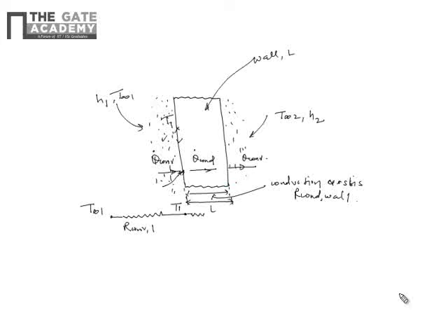Now the wall is offering some conduction resistance, and its wall temperature has dropped to T2 on the right hand side surface. Again at this surface there is one convection resistance on the right hand side that will cause the temperature drop, and as we know, the right hand side fluid temperature is given as T∞2, and this convection resistance is, let's say, convection 2.